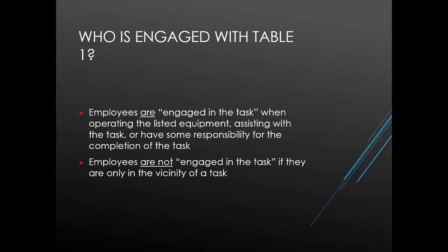So who is engaged with Table 1? Employees are considered engaged with the task when they are the one operating the listed equipment, assisting with the task, or have some responsibility for completion of that operation. Employees in the vicinity of a task are not considered to be engaged in the task, but if they have exposure, the employer is still responsible to ensure they are not being overexposed to silica.